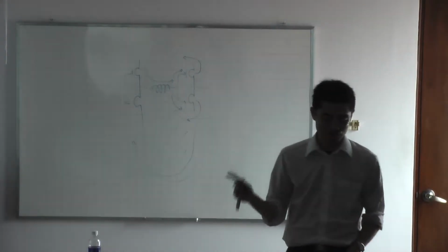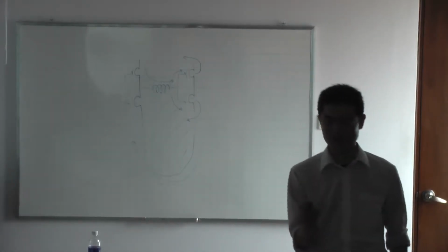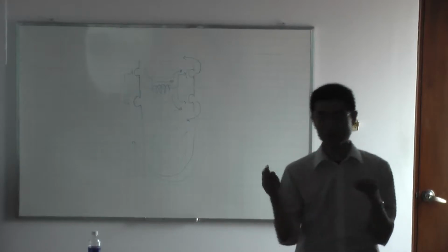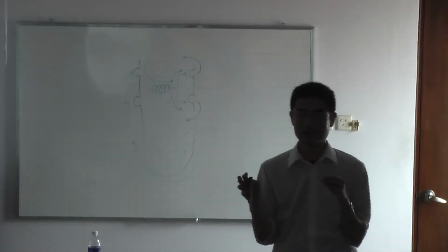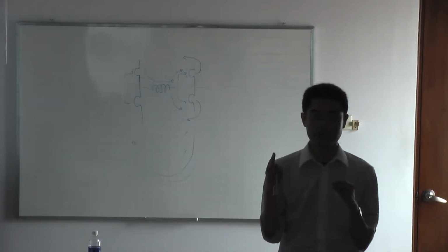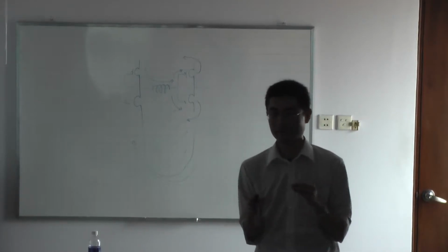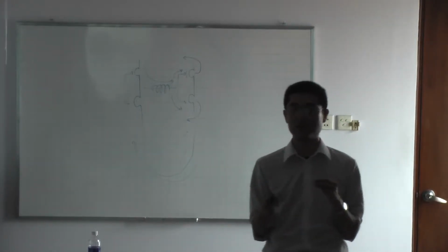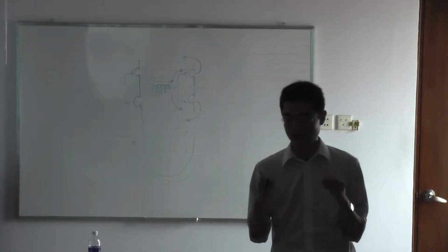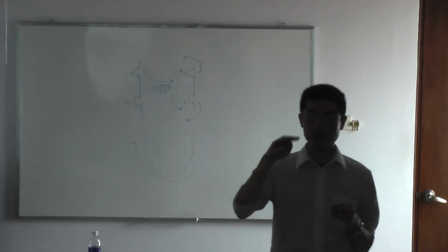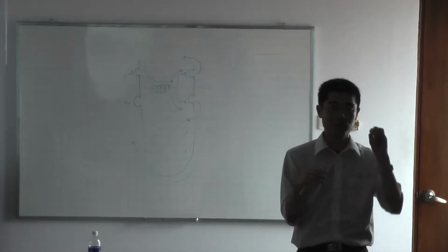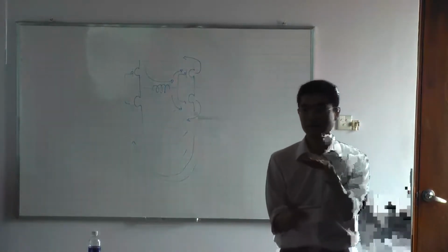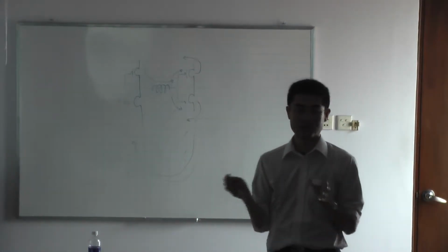And it's also used at the input terminal of measurement devices, for example, spectrum analyzers. The input of a spectrum analyzer is also very sensitive, and what we are concerned about for a spectrum analyzer is the frequency component. So the DC component, we don't care about it. We only consider the AC component and frequency component. Also, because it is very sensitive, the maximum input voltage is limited. So in such a case, we put a DC blocking capacitor to block the DC, and the whole signal comes down around 0 volt, so that it protects the measurement device from damage.